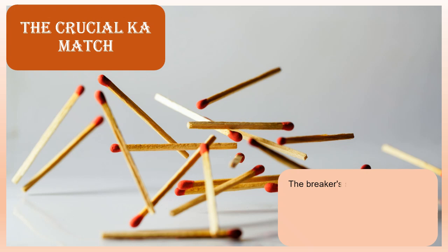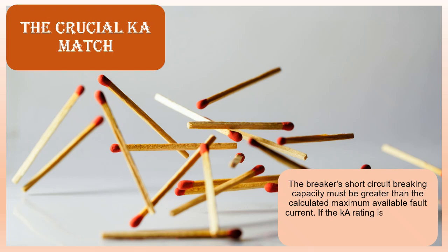The crucial rating match. The breaker's short-circuit breaking capacity must be greater than the calculated maximum available fault current. If the rating is insufficient, the breaker is unsafe and could fail violently upon a short circuit.